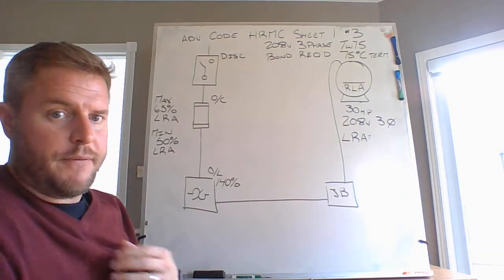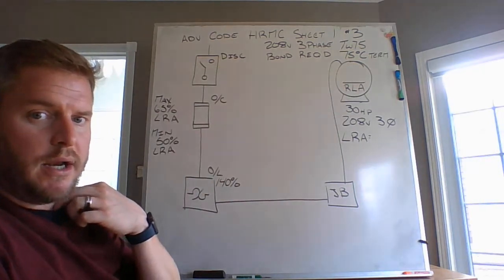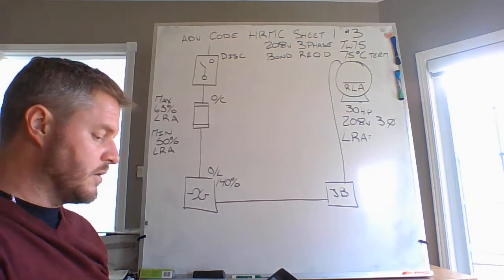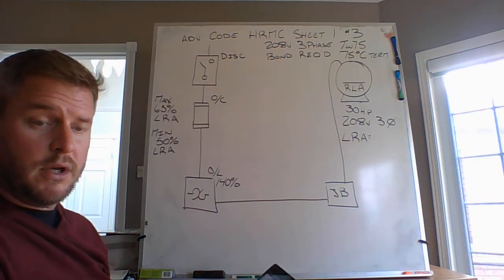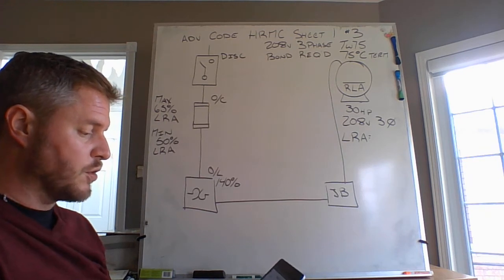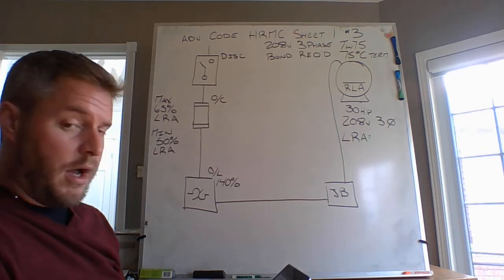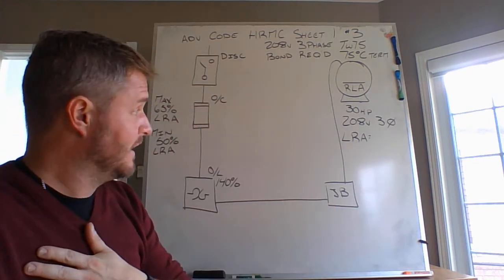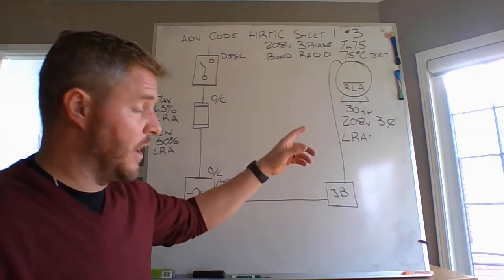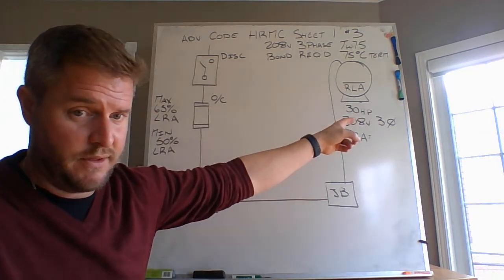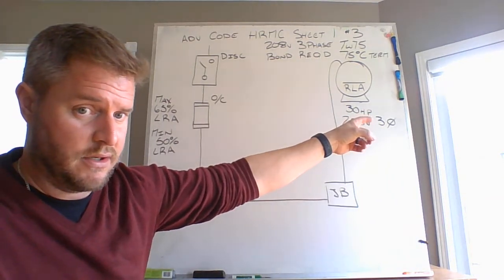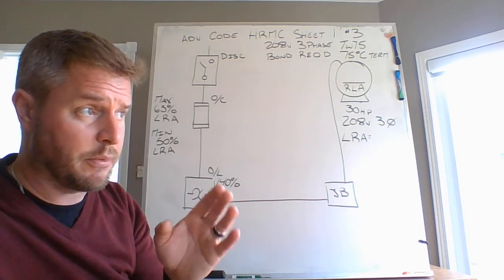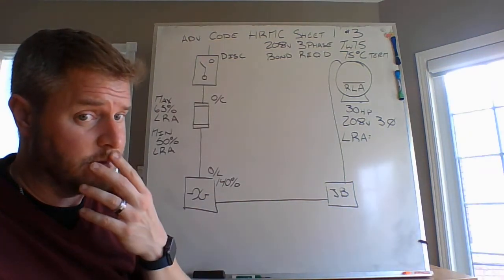All right, and if you pull up your examples that you have on Fanshawe Online, we're going back to a 3-phase calculation coming from sheet number 1, hermetic refrigerant motor compressors, and we are doing number 3 on that sheet. We're looking at 3-phase hermetic refrigerant motor compressors. Now, another little memory aid here. Be very careful when you're looking at these values, specifically 3-phase. It could be single phase. Be very careful with that. That's the difference between table 44 and table 45. Big difference, okay?